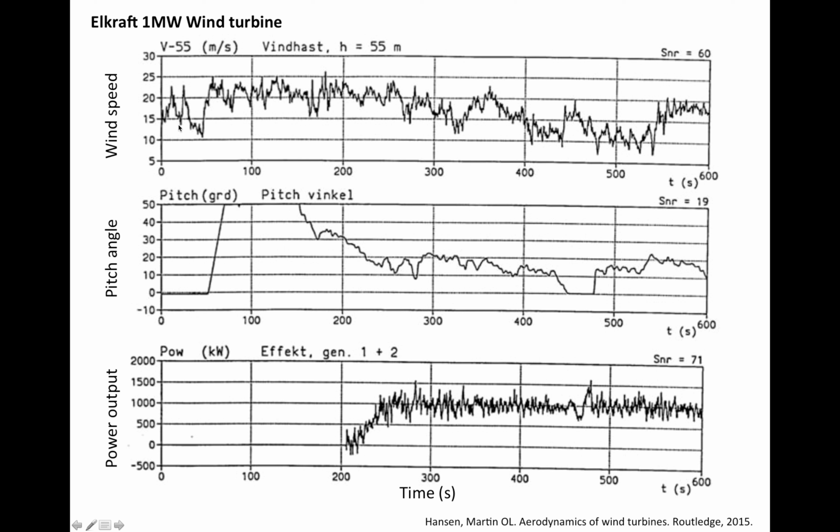The wind speed is actually very high, right? It's close to 20 meters per second. It's close to the cutout speed already. So the wind speed is very high, and it fluctuates rapidly with time. You can see lots of high frequency content in the wind history curve.